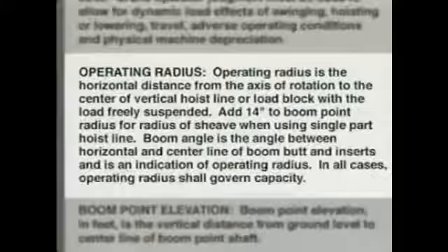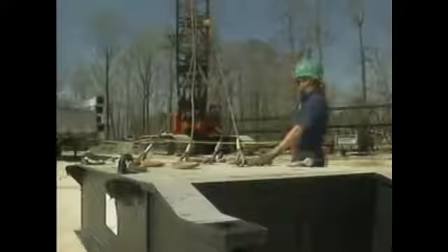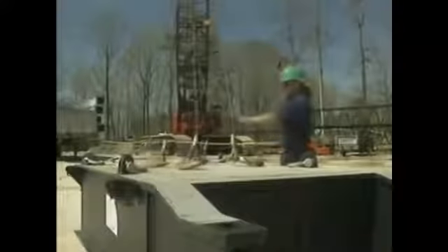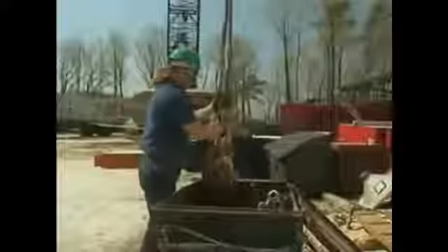When the load is directly above its appointed destination, it's slowly lowered into place. To complete the job, the rigger disconnects the lifting lines, signals the crane operator to move the lifting hook out of the way, and returns the rigging equipment to its proper storage place.